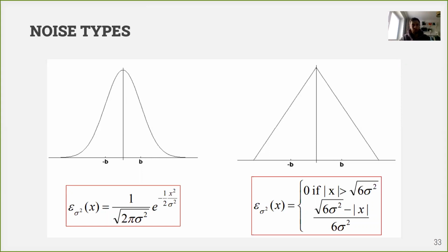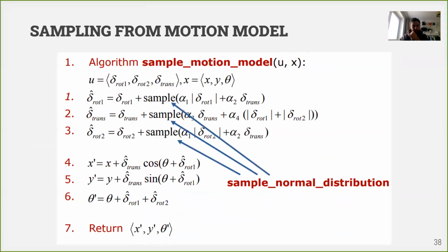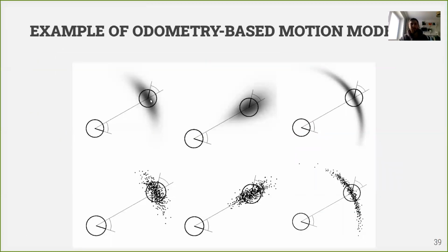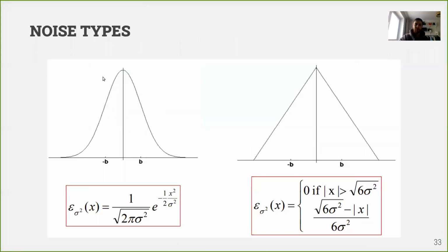They try to move the robot 1 meter, for example, 1,000 times, and they get some distribution like this one, right? And having this distribution analyzed experimentally, they try to recover this noise model, because you don't have any other technique to estimate your noise model, only experimentally.